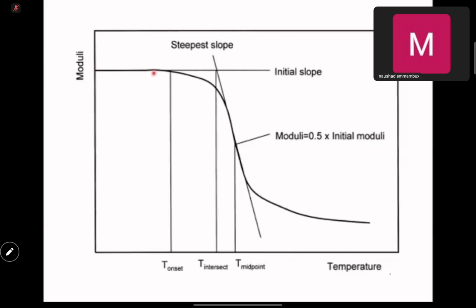It will be high modulus at the beginning. As you increase the temperature, it softens because there is a change in terms of the glass transition. There is already a shift from vibration to translation, to rotation and translation, and then your material becomes more amorphous, and then the moduli decrease. You can compare different materials using rheology if you do a temperature sweep.